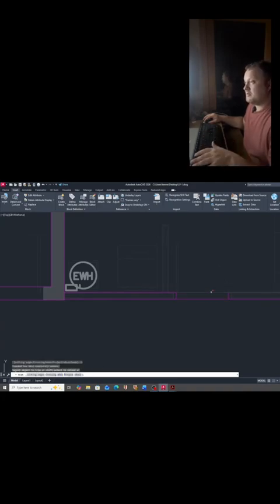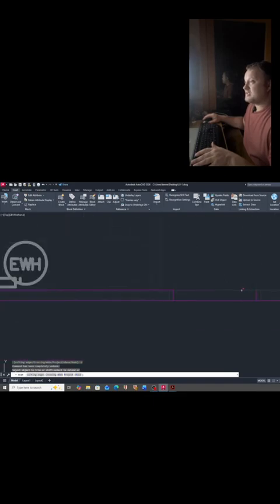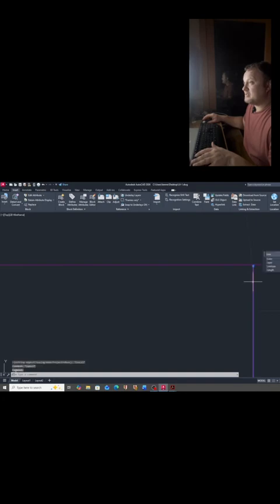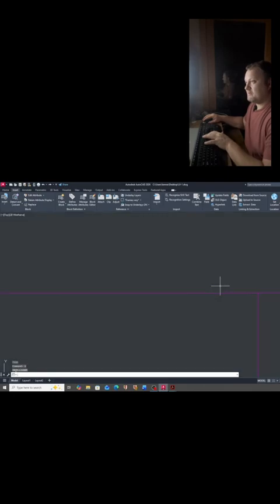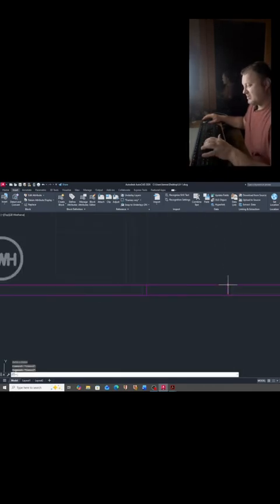I'm going to undo. So the fact that it's not just stopping at this line tells me that this line is not touching. So I always drag past and then come to the point, and let me hit undo just so you guys can see again. So I went to trim this, TR, enter, and if I select here, it stopped at the 2 crossing points.